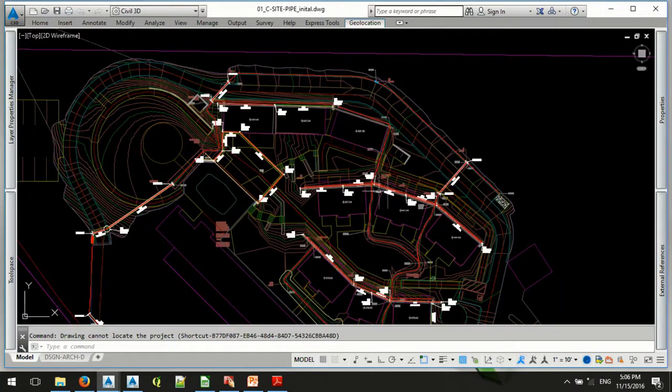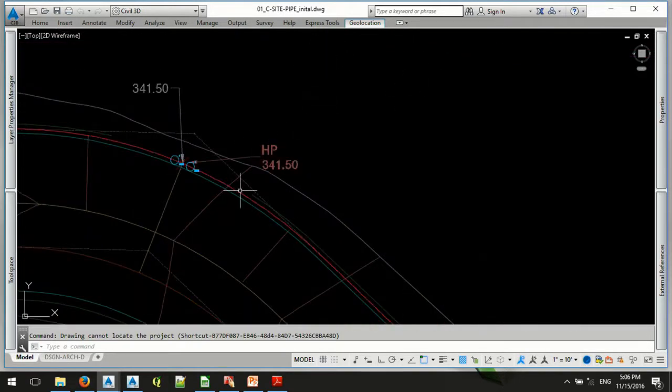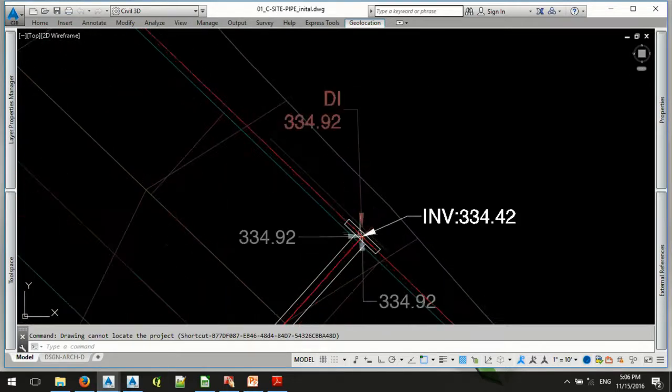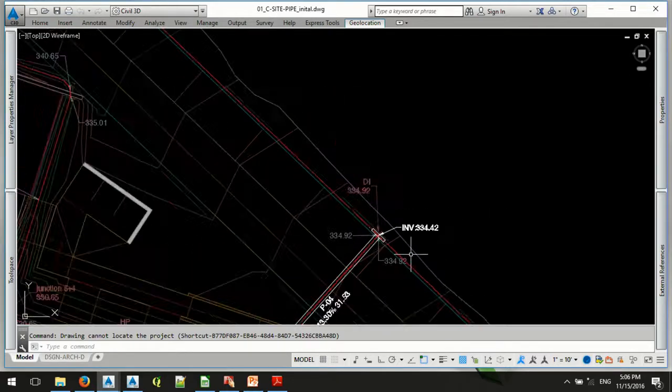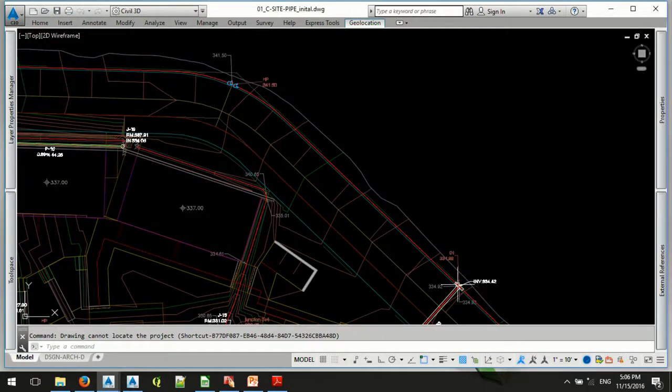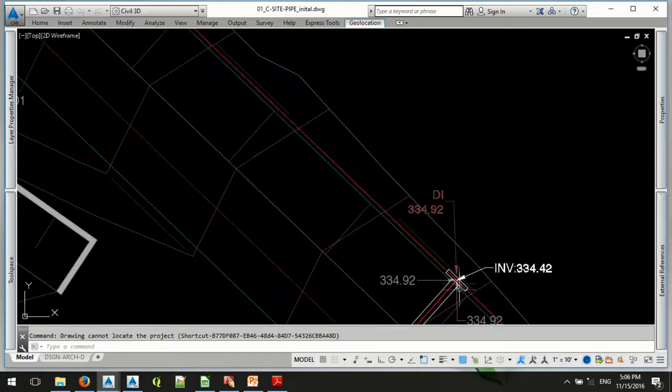These are all of the buildings here. These are the different terraces that we've kind of roughly graded into the hillside. And this is a service road that goes around the edge. There's a massive mountain on this side, and it's going to flow down and get intercepted in this swale. So this is the high point of the swale, and it drains all the way here into this culvert and passes underneath the road. So we're going to lay out a demo open channel between the high point and the inlet. This is a typical classic Civil 3D pipe object.